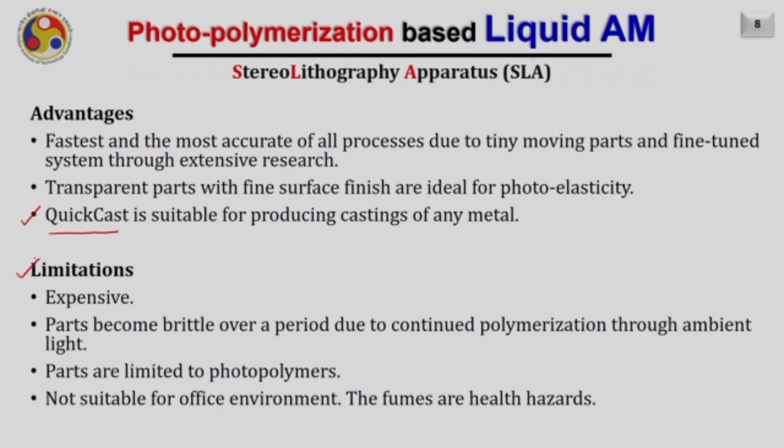There are a few limitations, of course, for the process. It's a very expensive process because of the involvement of laser and the requirement of the liquid. This is another very important point. As you have seen, even if you want to create a very small part, the entire tank has to be filled with the liquid resin. Otherwise, you will not be able to recoat the new layer. That is why, because of the involvement of a lot of raw material also, the process is quite expensive.